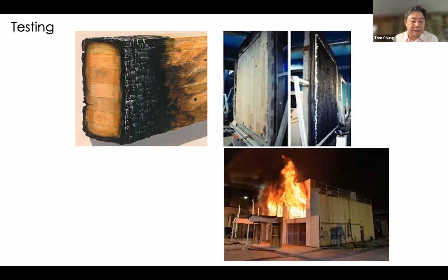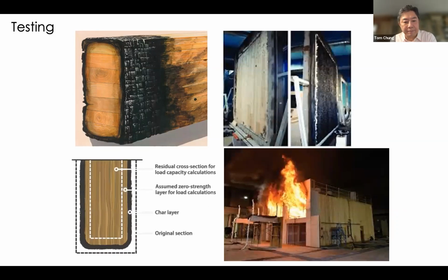So the IBC code of the Type 4 category, for example, for heavy timber construction has now expanded to 3 different categories to include up to 18 stories of building height in wood and mass timber prescriptively. And as more testing is done and more mass timber buildings are built, that height and those limitations will continue to expand and expand.